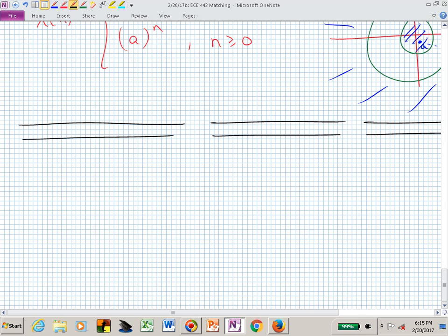And that would be the dominant pole. Typically, you want that pole to be closer to z equal to 1. If it was close to -1, it's flip-flopping back and forth. It's erratic, but I prefer to think of the poles near z equal to 1 dominating the response.